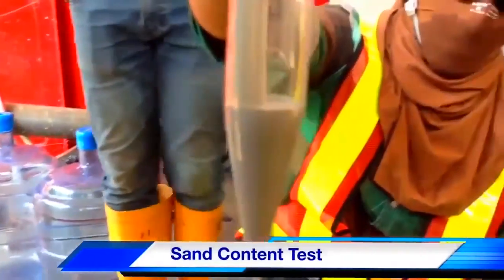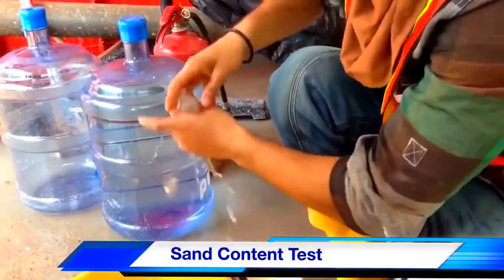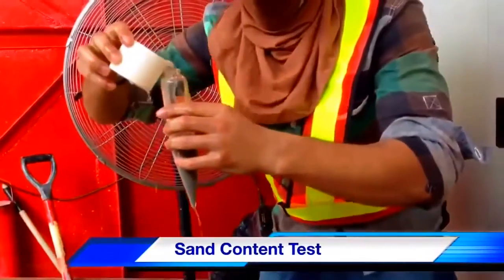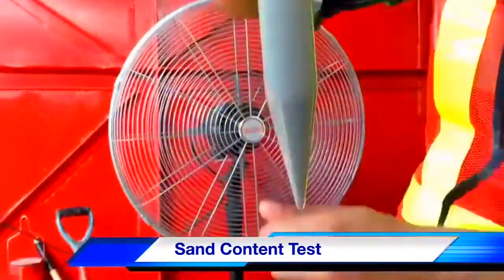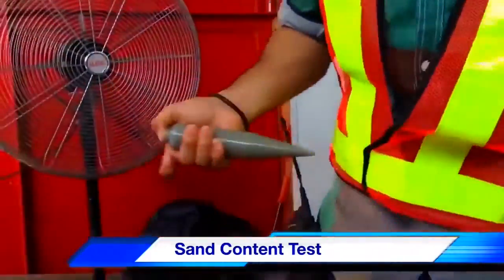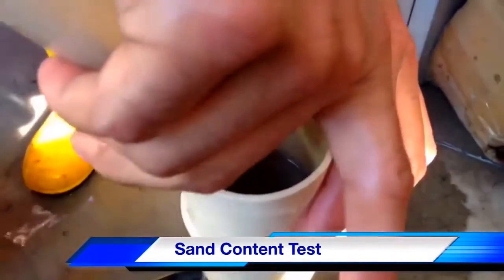The sand content test is another important test which is used to check the properties of bentonite. Then the bentonite is poured into the apparatus until it reaches the end of the conical shape. The sand content apparatus is filled with water and shaken well. Then the water is passed through the net of the apparatus and sand is collected.